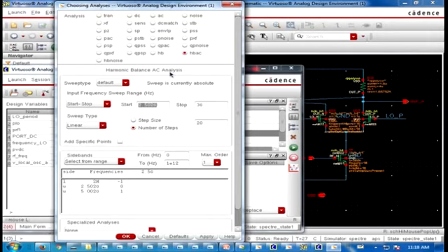So you have to give what is actually the RF frequency here, and you want to sweep the RF frequency from some region to some region. Of course, that region should contain the IF band. So here I am just going for the stop band of 3G. It's normal AC analysis, where I would have to go from 1 hertz to 1 terahertz or something to capture all the bandwidth. Here I have to go for only 2.502, let's say this is my actual RF frequency, to 3G, and then the number of steps I have to give is 20.